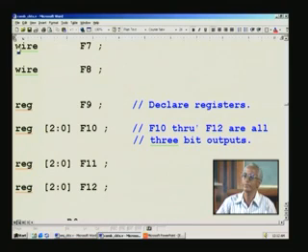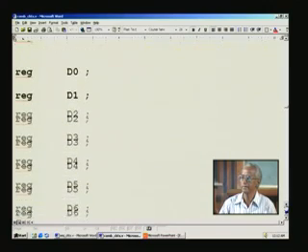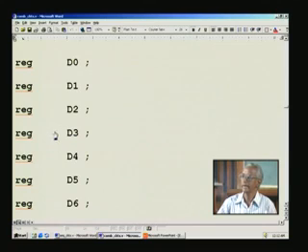So for assign statements you can say wire, and for always block, whatever output, all are with reference to the outputs only, not the inputs as such. And you can refer to as a reg in always block whatever signals come in that. Once again you see here for reg multi-bit it is through this, and for single bit we have this.